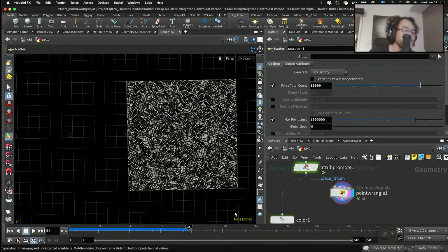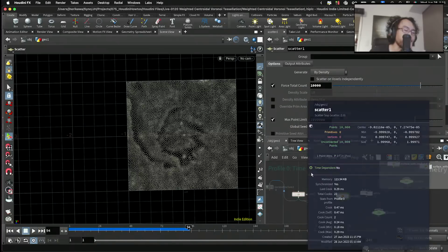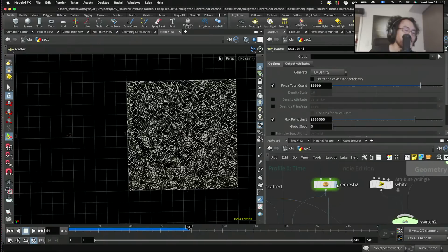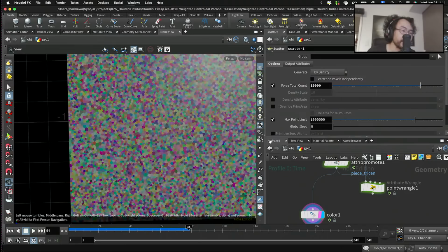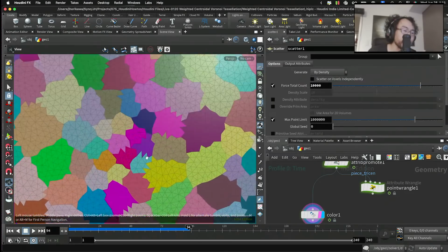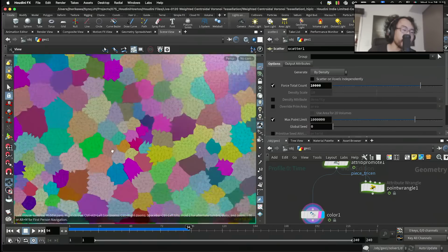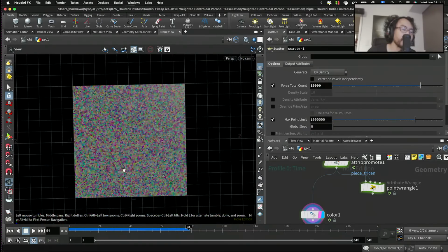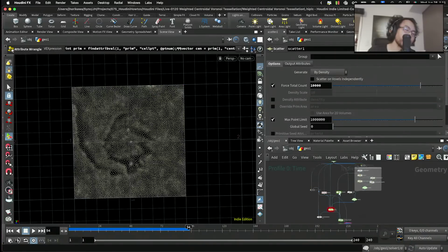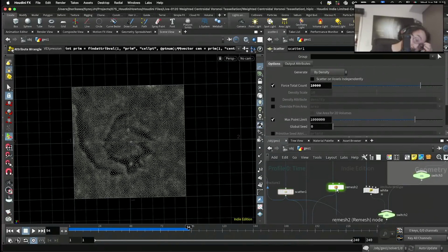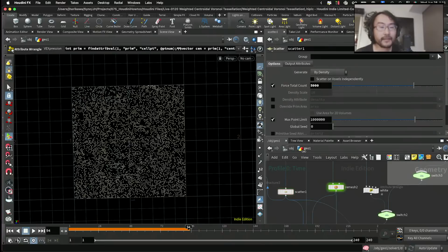But if you have more points, you might need more resolution for the sampling mesh. As you can see, this one is pretty low res. And if you increase the mesh number, then you get slower results. So you gotta find a good balance between them. Anyway, that's how we could do it.